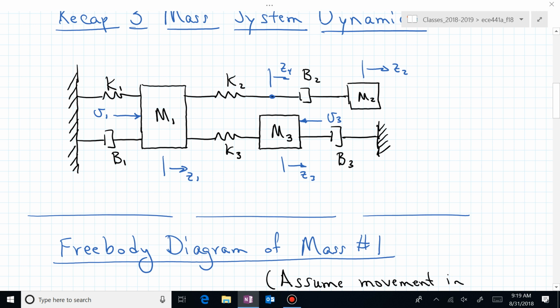There's a force opposing that, and that's F1 sub k sub 1. And it only depends on the one end, the right-hand side, because the left side is fixed. It's an immovable mass. And we're just worrying about the spring force, which is dependent on the elongation or contraction of that spring. If we pushed z sub 1 in the negative direction on that spring, which way would the force be?